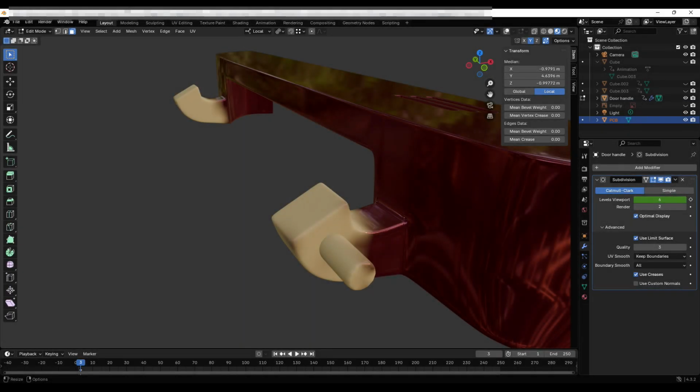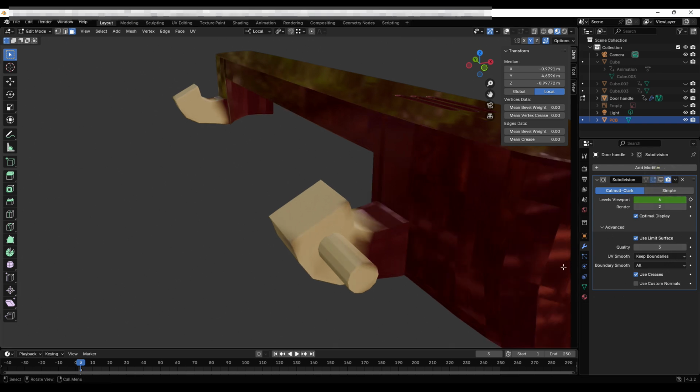CapExt imports 3D models as STL files. Make sure the resolution of your model is limited. Remove all heavy interpolation subdivisions to reduce the number of polygons for CapExt to process. If not, your model may not import. In Blender, this is done by making sure you export the model without the subdivision visible and before it is added as a permanent modifier. If your CAD tool has the option of permanently adding subdivisions, you need to branch off a 3D model for CapExt before this operation is carried out.